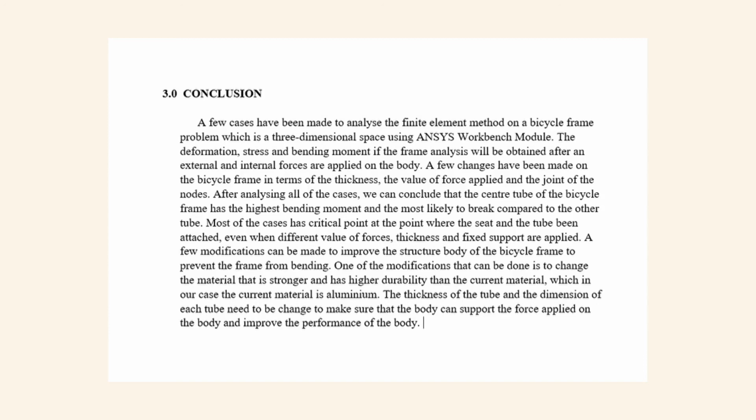After analyzing all of the cases, we can conclude that the center tube of the bicycle frame has the highest bending moment and is the most likely to break compared to the other tubes. Most of the cases have the critical point at the place where the seat and the tube are attached, even when different values of force, thickness and fits are applied.